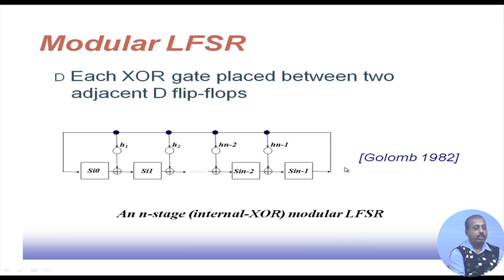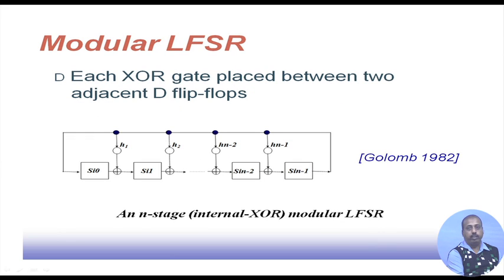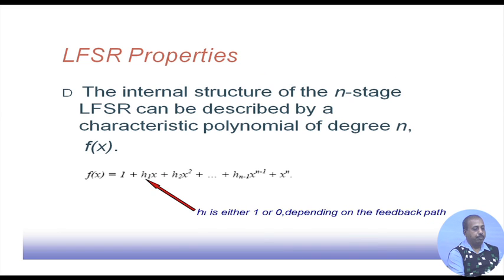Though functionally this modular LFSR and this external XOR LFSR, the standard LFSR, are going to be the same, both of them can realize a similar set of functionalities, but both the structures are there. There is a very strong theory based on polynomials that can describe the properties of these LFSRs.